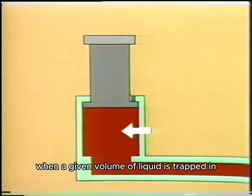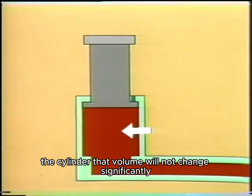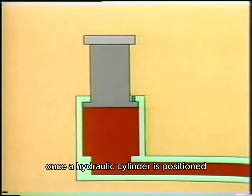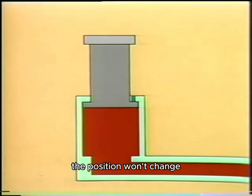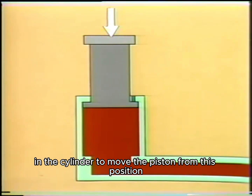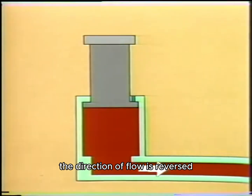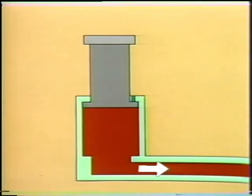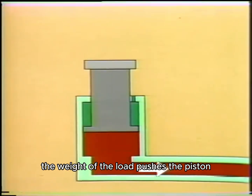When a given volume of liquid is trapped in the cylinder, that volume will not change significantly in spite of any force or weight provided by the load. Once a hydraulic cylinder is positioned, the position won't change. Unless fluid leaks out, downward force will have an insignificant effect on the position of the piston in the cylinder. To move the piston from this position, the direction of flow is reversed. Liquid flows out of the cylinder through the port. The weight of the load pushes the piston back to its original position.